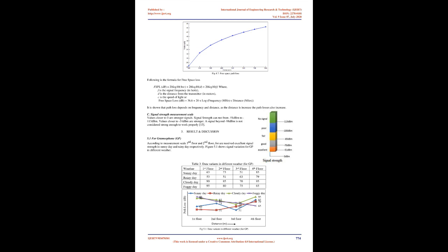The received signal strength, RSS, plays a very crucial role in determining the nature and characteristics of location fingerprints stored in a radio map. The received signal strength is a function of distance between the transmitter and receiving device, which varies due to various in-path interferences. The measurements are performed for horizontally and vertically positioned mobile terminal at different times, in order to distinguish between the vertical and horizontal components of the received signal. Although the received signal increases for higher levels, its strength is not uniformly increasing above floor.